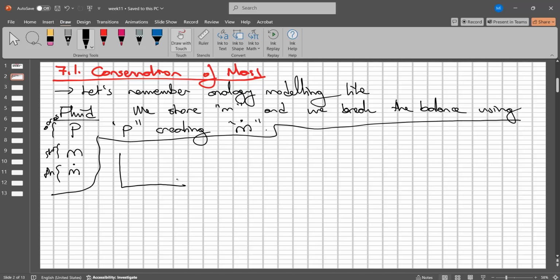Suppose that we have this tank system just like this one, and also we can create the m in dot in here, and so we can define the P out as the P ATM, because as always we should use this one because the atmospheric pressure is everywhere. Okay, and also we can write the resistance in here because it's a pipe, and the narrowing of the pipeline induces the resistance. It resists the passing flow in this case.